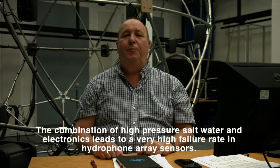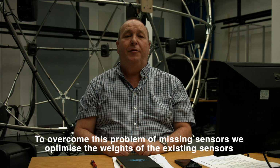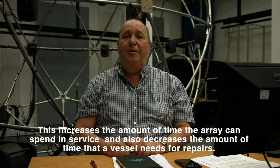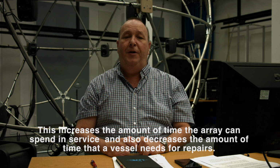The combination of high-pressure salt water and electronics leads to a very high failure rate in hydrophone array sensors. To overcome this problem of missing sensors, we optimize the weights of the existing sensors to take into account these damaged sensors. We try to maximize the performance of this damaged array. This increases the amount of time an array can spend in service and also decreases the amount of time that a vessel needs for repairs.